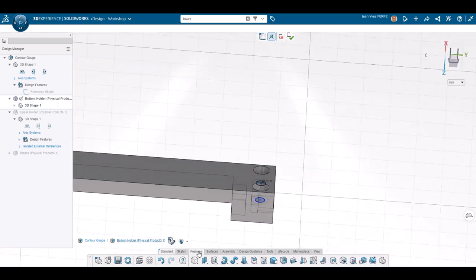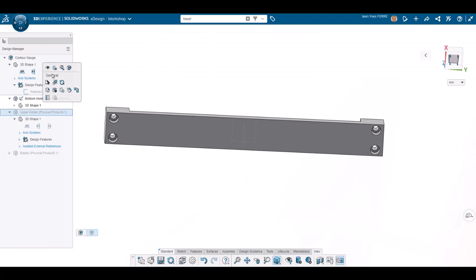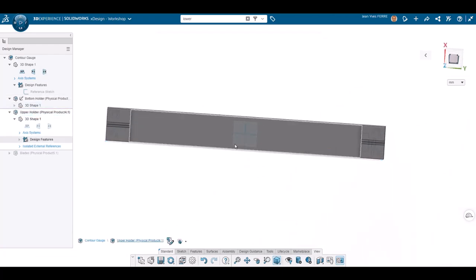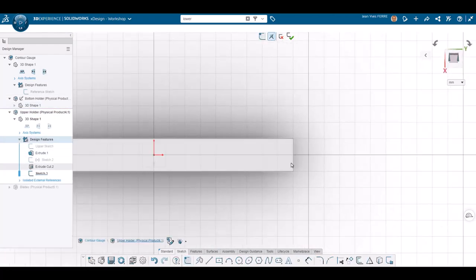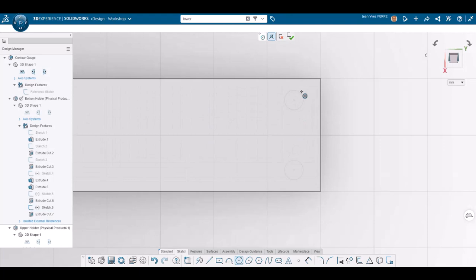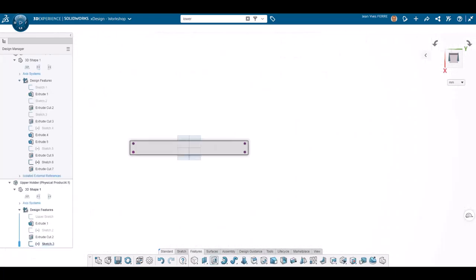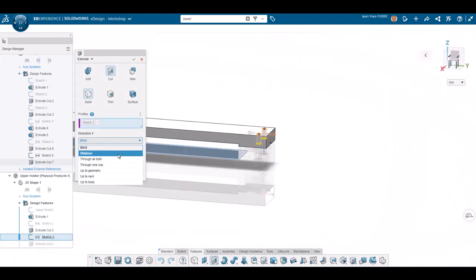We saw the lower part has a clearance to let bolts move freely, but in the upper part I will save nuts using smaller holes than the bolt. So the bolt will create its own thread to stay in place. For M3 bolts, I use 2.8mm holes. Of course, I projected the lower part holes to make sure everything is aligned without adding disconnected dimensions. Holes are cut through, so they will adapt to any future thickness change.